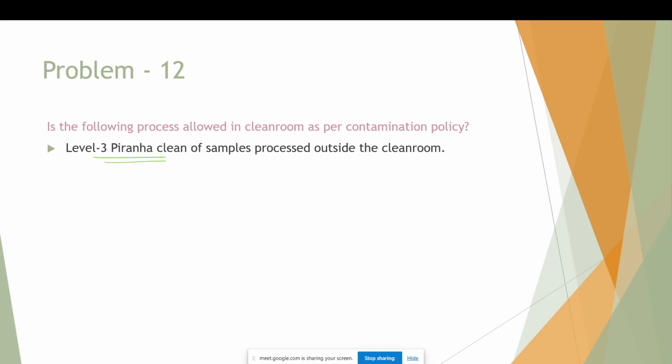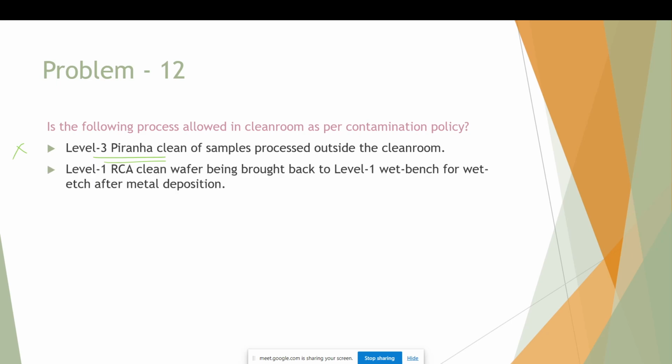No. Okay. Yeah, so all of you have listened to the videos. That's nice. Next: RCA clean wafer being brought back to level 1 wet bench for wet etch after metal deposition. So you had a new wafer that was level 1, and you did an RCA clean on it. After that you did some metal depositions along your process flow.